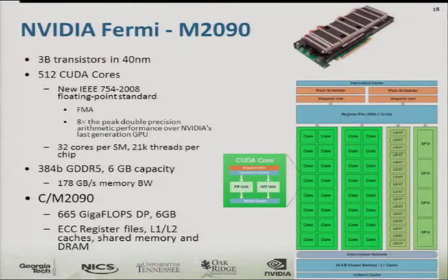And that's configurable. One of the interesting things we've been doing is running some of our applications with ECC on and ECC off, because you can turn it on and off with firmware, just to see how much faster it is. In some cases, the applications actually run faster, and we're trying to understand if there are some apps we can run all out without ECC and know that there's an error if there's an error in the execution. And you get higher throughput that way.